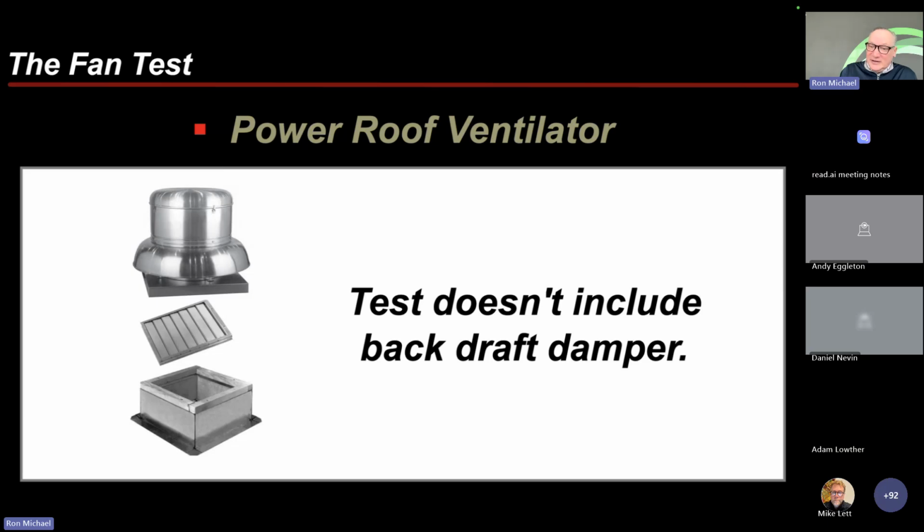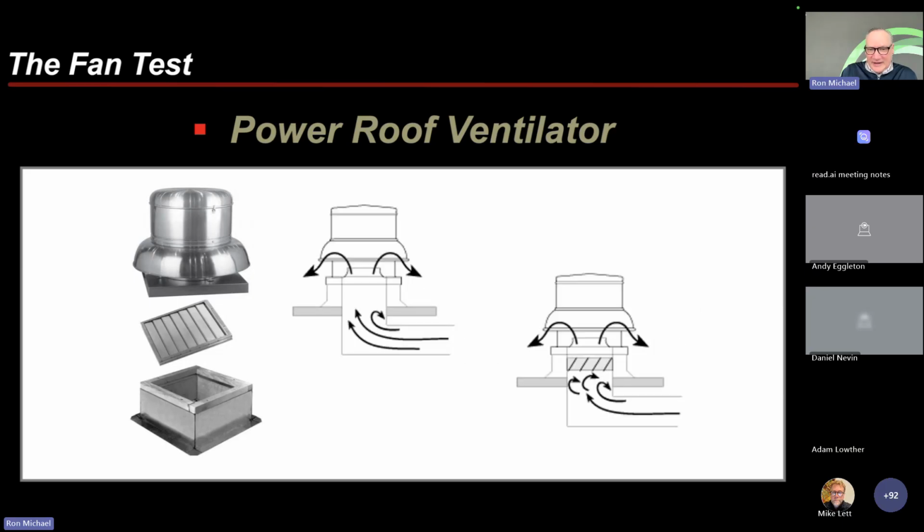I freely say if I never had to sell any inlet or discharge damper on any of my fans, I would be pretty happy. Anything that immediately blocks the inlet or the discharge is a restriction. We offer the accessory mainly because other manufacturers do, but it's not necessarily a great idea.